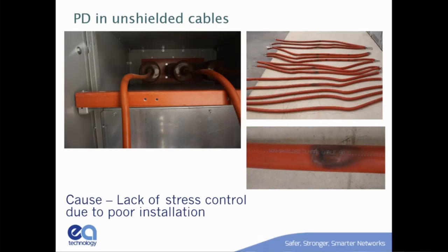The switchgear manufacturer said this installation is fine. The customer high-potted it, and it was fine. They measured it, and it was fine. Within a month of energizing it, they had audible ultrasonic discharge, and you can see from this picture, within a few months, they had to replace all those cables and reroute them. This is a clear indication of where your typical installation looks okay, or the typical tests are all okay, but clearly this was going to fail in a pretty short period of time. This is a very super critical installation, and they put in full-time monitoring on every cabinet, and they found this long before it led to failure.